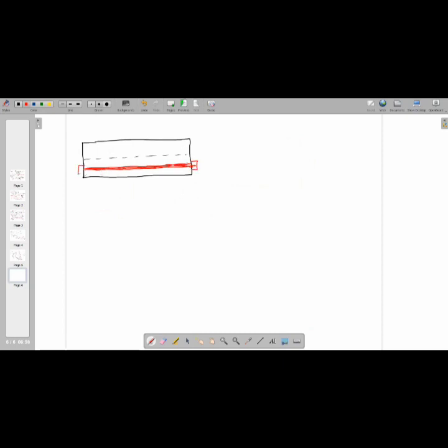Here you have a pre-stressing force. In this case, we also have a dead load and a live load. So see students, if you see the stress distribution, it will be load by area. This is due to direct stress, the stress due to load.